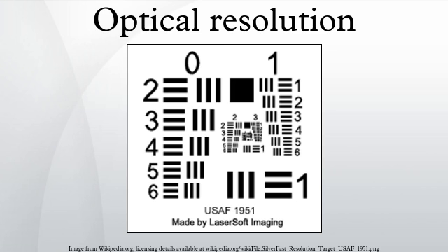ISO 12233 target: The ISO 12233 target was developed for digital camera applications, since modern digital camera spatial resolution may exceed the limitations of the older targets. It includes several knife-edge targets for the purpose of computing MTF by Fourier transform. They are offset from the vertical by 5 degrees so that the edges will be sampled in many different phases, which allow estimation of the spatial frequency response beyond the Nyquist frequency of the sampling.